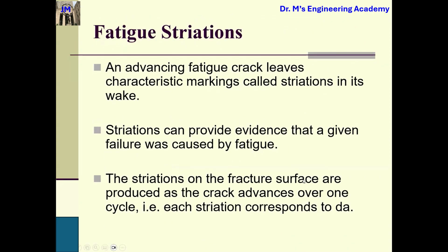So, fatigue striation. We can show you what the breaking surface looks like. An advancing fatigue crack leaves characteristic marks called striations in its wake. It's very beautiful. I'm going to show you a picture. Striations can provide evidence that a given failure was caused by fatigue.